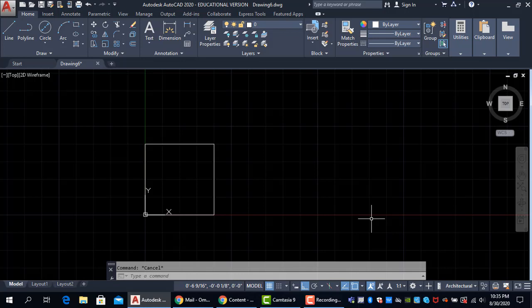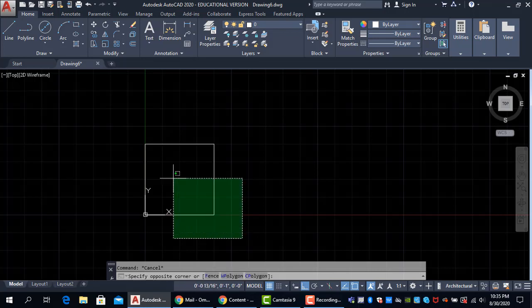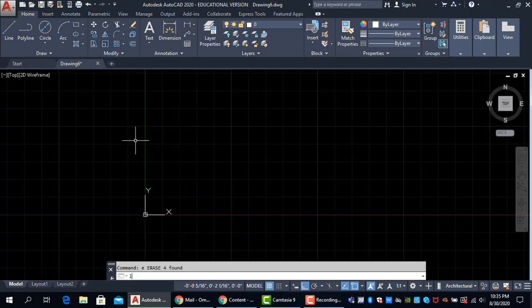So in AutoCAD, we need to specify that. Just FYI, if you're in the architectural units, whatever number you type, it's going to see it as inches if you don't specify. For example, let's do this again. I'm going to do a line, 0, 0. If I just put 2 this way, just like that, enter, it's going to be 2 inches. 2 inches, 2 inches, and then close.